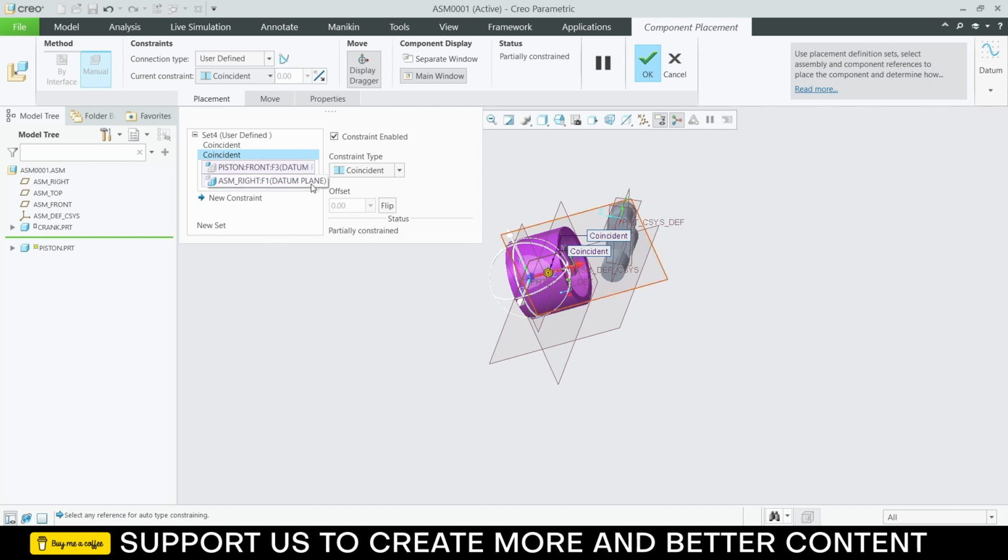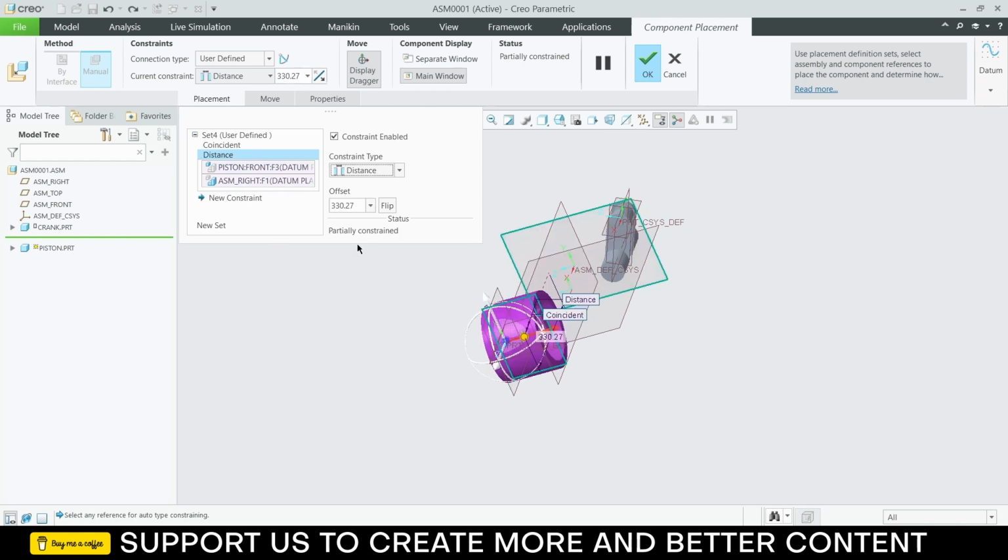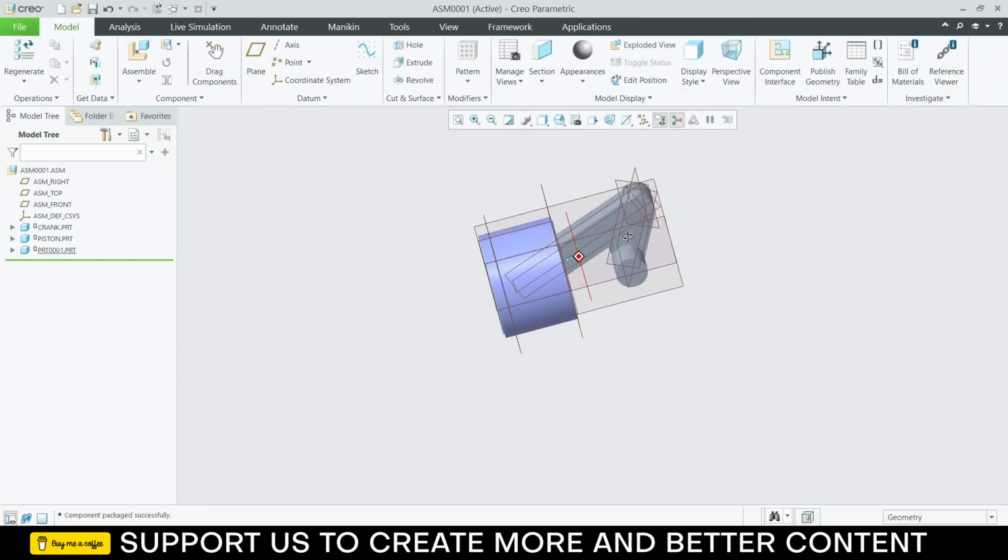I was wondering, press Control Z. I accidentally didn't use new constraints, so make sure that you use new constraints. I don't want to modify the previous constraint. I already made that mistake once. Click on coincident. Click OK.